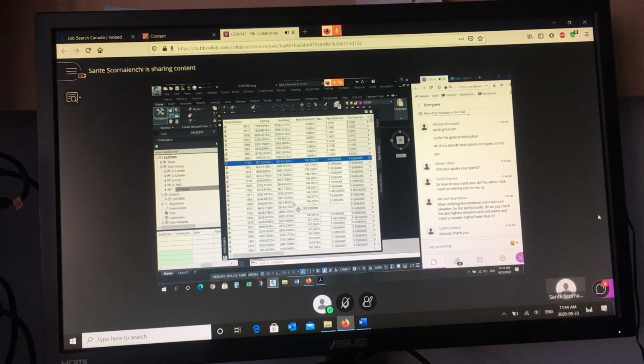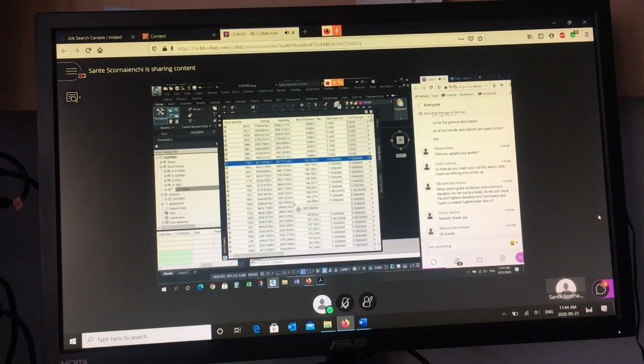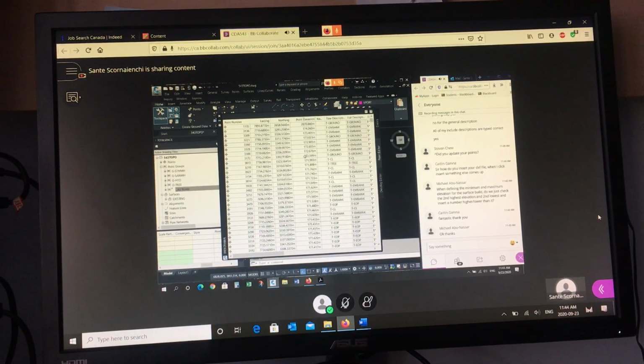So all numbers less than 100 will eliminate the zeros. And then if you sort it again, you'll see a bunch in a certain range, and then one of them will be way out. So then you pick a number just above this, let's say in my case 200. Anything above 200, ignore it, and then it'll get rid of the high spike. Okay, so you have to sort the point elevation column to see what number you should use.